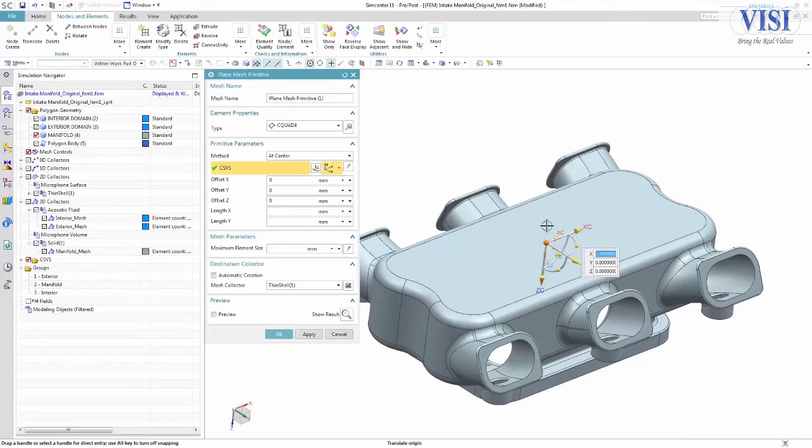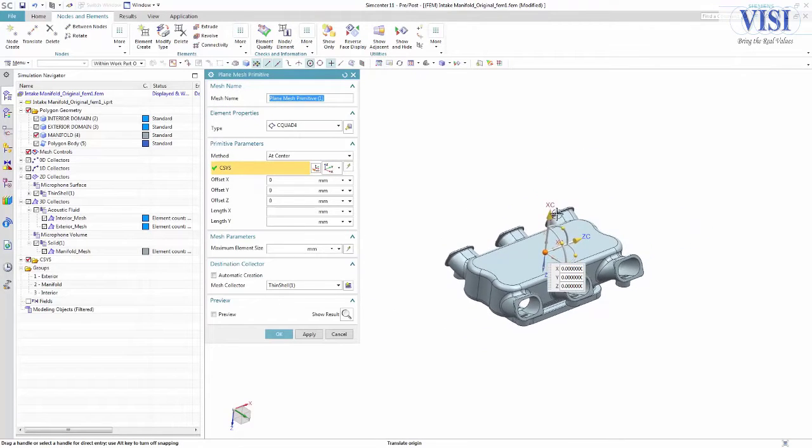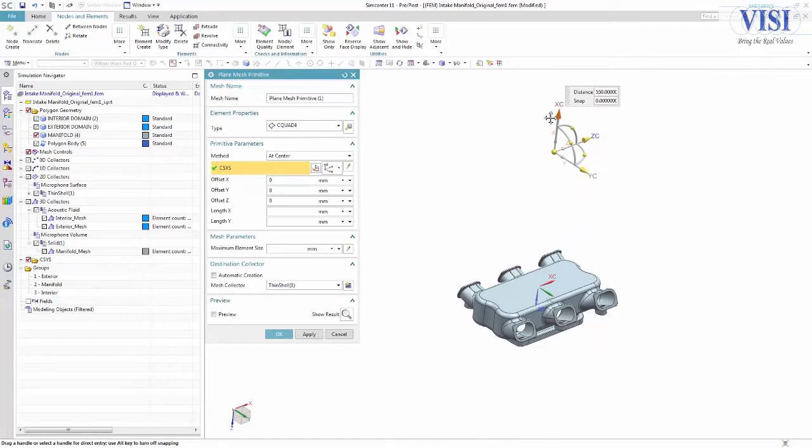Lastly, you need to define a mesh that will represent the microphone surface above the manifold. Once these meshes are defined, they can be assigned their material properties and you can add the loads and boundary conditions.